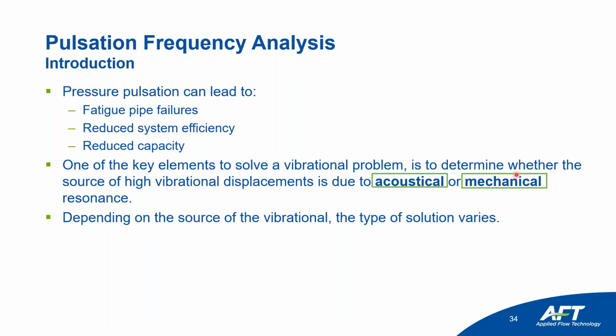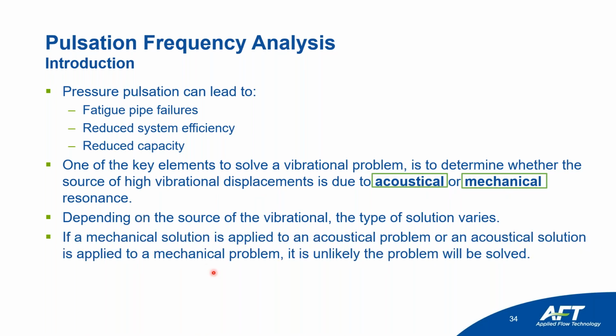Another mechanical solution can also be changing the location of your supports. As I said, you have to determine whether you have an acoustical problem or a mechanical problem and use the proper solution. Why? Because if a mechanical solution is applied to an acoustical problem, or an acoustical solution is applied to a mechanical problem, it is unlikely the problem will be solved.